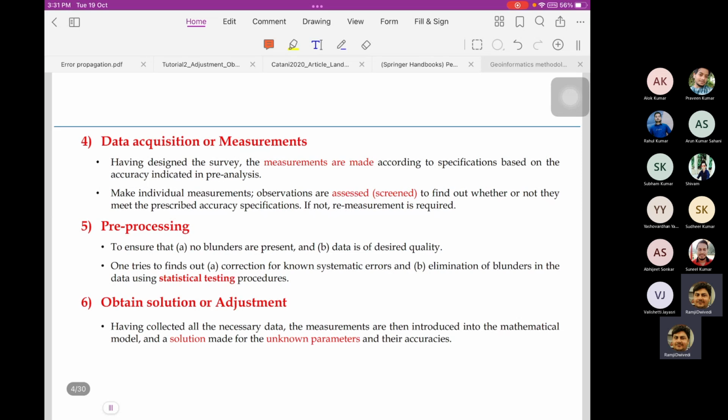Whenever we go into the field for any project work, we have a meeting in our office to discuss how to approach the individual days with different types of tasks. You have to collect GPS data, you have to perform the TLS laser scanning, then you have to work with the total station. So we discuss step by step.